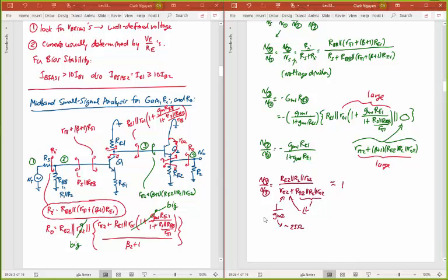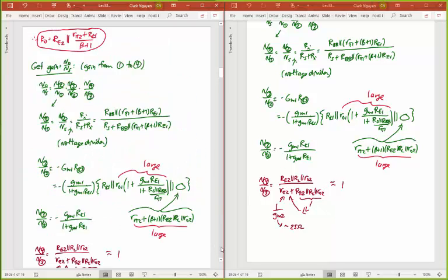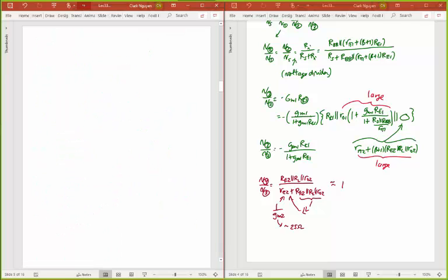And so with all of this, calculating all that there, and putting all of these gains together, there's my first gain up here, there's my second gain right here, there's my third gain right here, I can write out the whole gain for this problem, which I'm going to do right here, and just say therefore, so rewriting this, V0 over Vs, that's equal to all of these gains multiplied together, so V of 2 over V of 1 times V of 3 over V of 2 times V of 4 over V of 3.